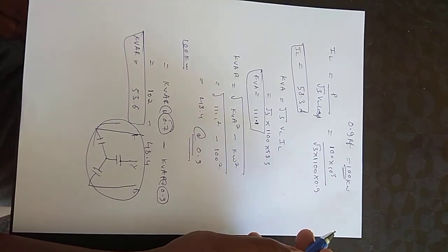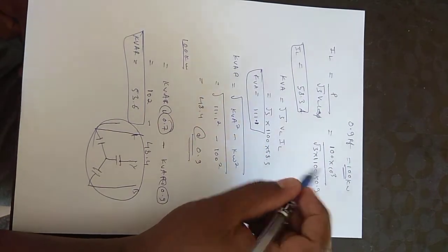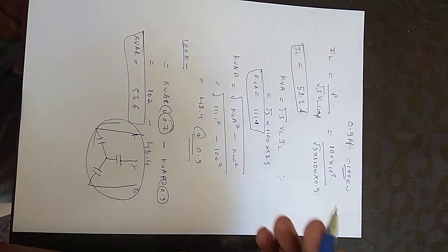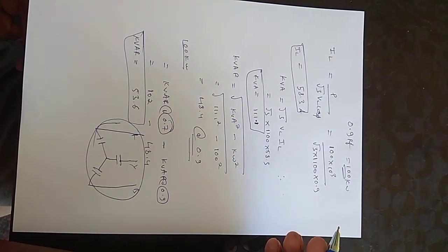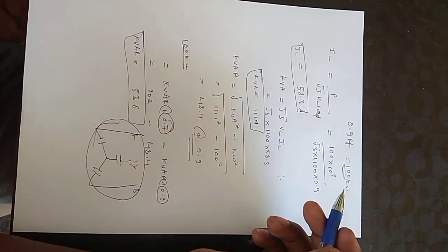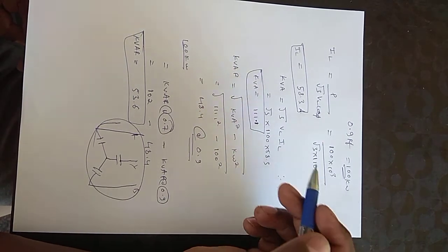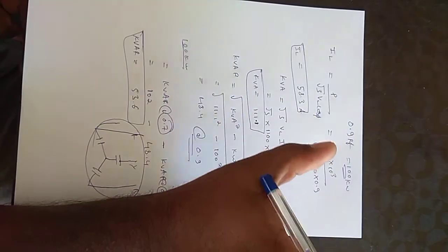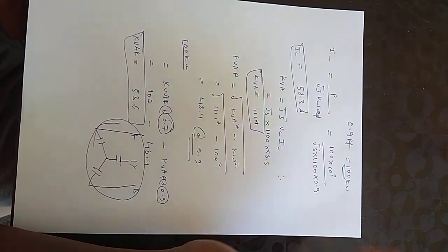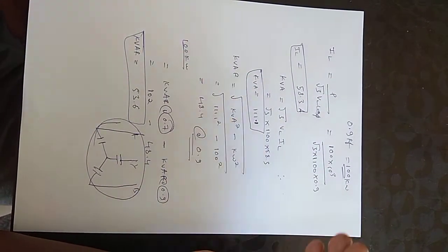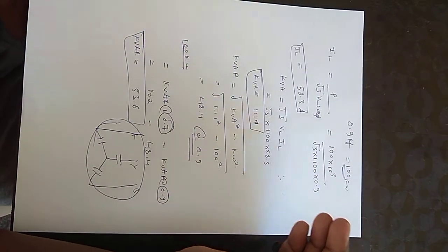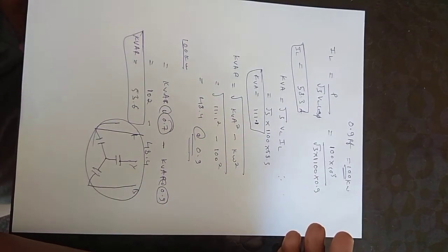In the next video we will see how this power factor capacitance I calculated now was for continuous duty. We'll see what power factor capacitance has to be added at starting. While the motor is accelerating, it takes higher current, and different motors have different acceleration times. The capacitance added for that is called short time capacitance. We'll see how to add short time capacitance for a given motor in the next video.